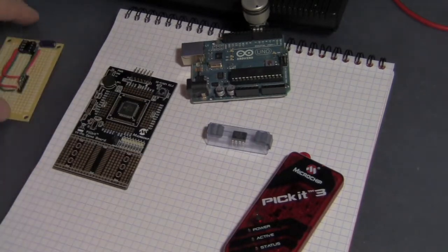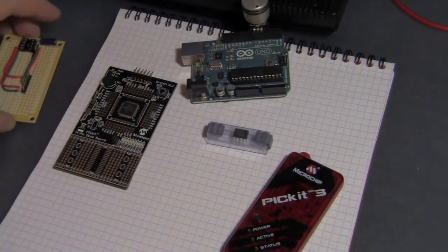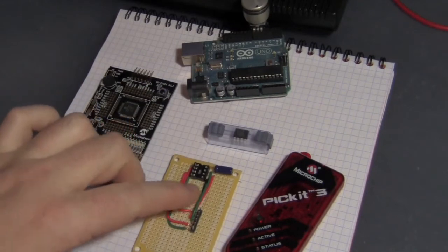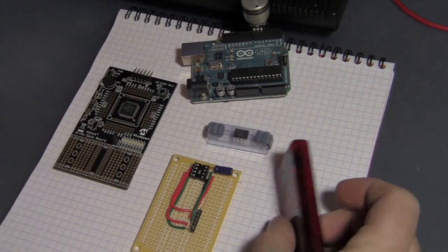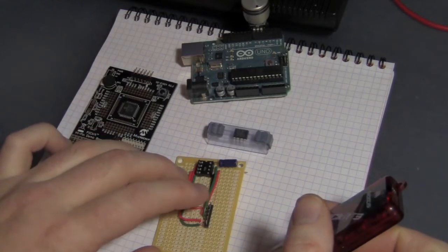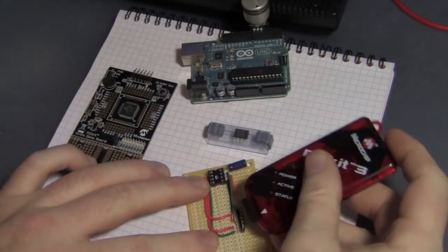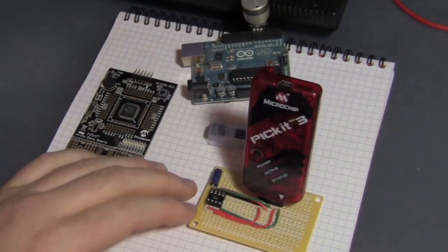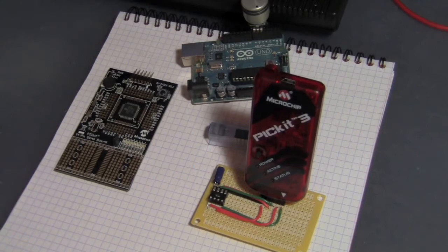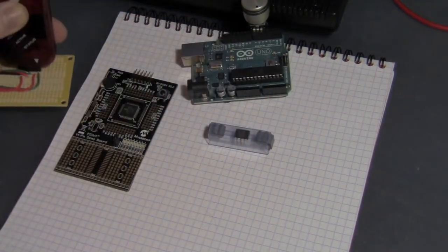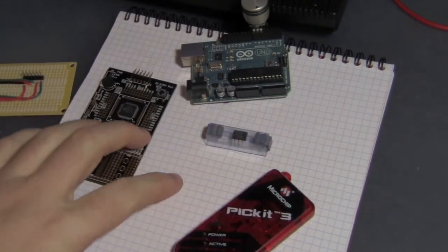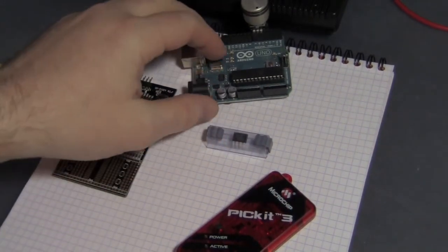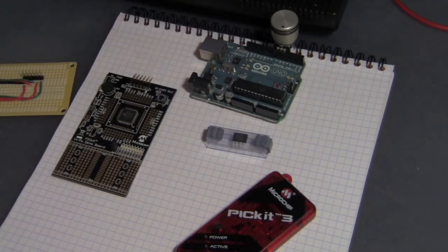So, to actually program this chip, I had to make a programming bed, and with the PICkit 3, it's incredibly simple. All you really need is some wire running from your header to a socket. You plug the PICkit 3 in, your USB to the computer, plug your chip in the socket, and program away. Altogether, the PICkit 3 kit is about 60 bucks. The Arduino Uno is like 35. So the price difference isn't that great. They're just two cool little things to experiment with.